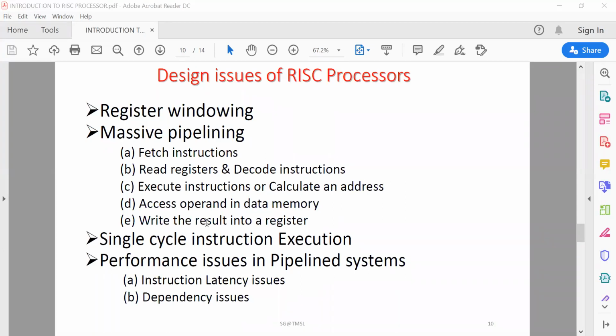those are instructions which instruct the processor to make a decision about the next instruction to be executed, depending upon whether the condition is satisfied or not. So a branch instruction can be troublesome in pipelining if it is conditional and may be taken, which has not yet finished its path through the pipeline. So in these two cases, it is very important to fix these issues.